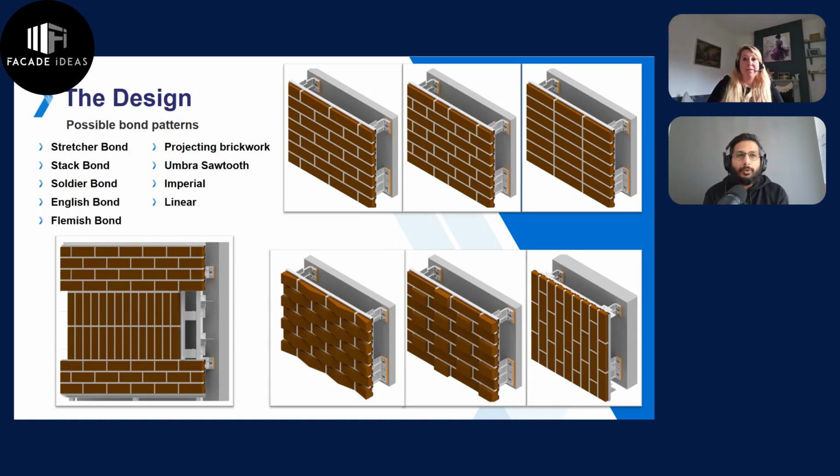If you're using just a brick, quick question. Sorry, I was in mid-flow. Go on, Mustafa. So could we cut these? If we were using the English bond, you need the queen brick in the middle. Would you make that queen brick and make sure you can adjust them on site with cutting the brick? And is that okay?